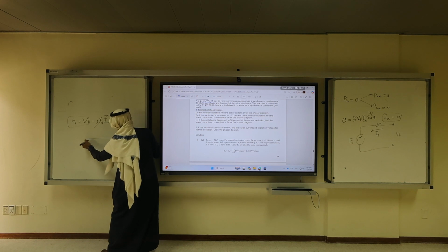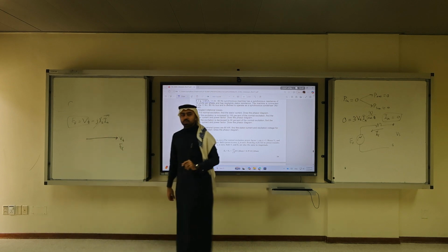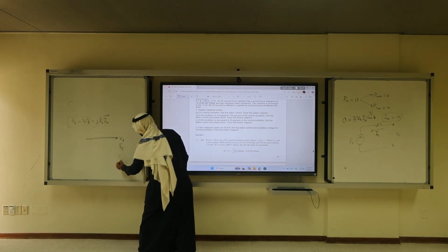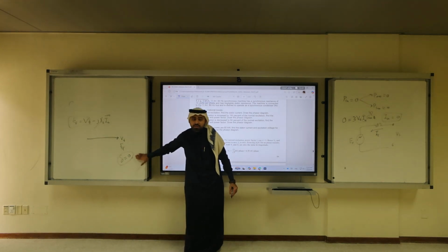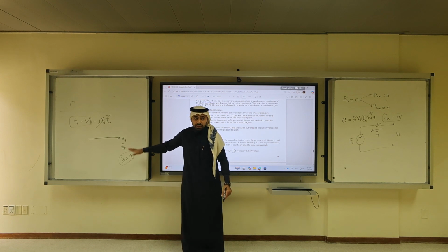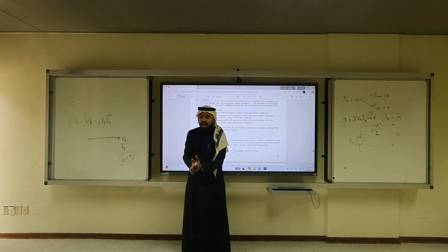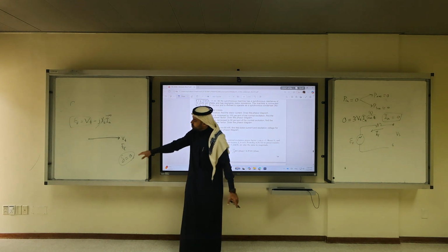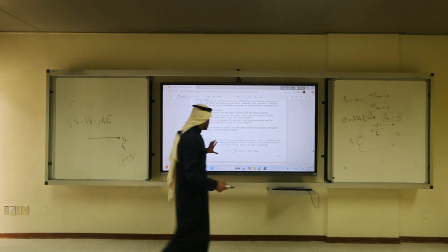IA is 0. So IF equals this, and what's my delta? Delta is 0. Is there any torque? No, no load, so the torque angle is 0. It matches the sense that I don't have any torque. The moment I add a torque to my system, delta would start to appear, which is the phase difference between EF and VT. Is this part clear?